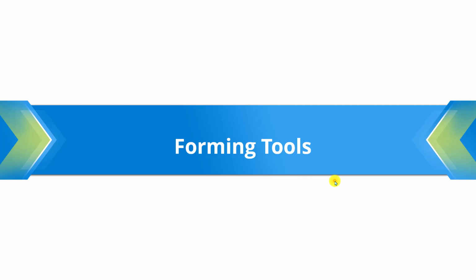In the next chapter, I'm going to introduce the forming tools. As we all know, there are features in sheet metal parts that need to be created by a punching die or drawing die procedure. So ZW3D provides tools to create such features, such as dimple, louver, and also we have a powerful punch feature to create dimple, louver, rib, etc. Now let's introduce them one by one.